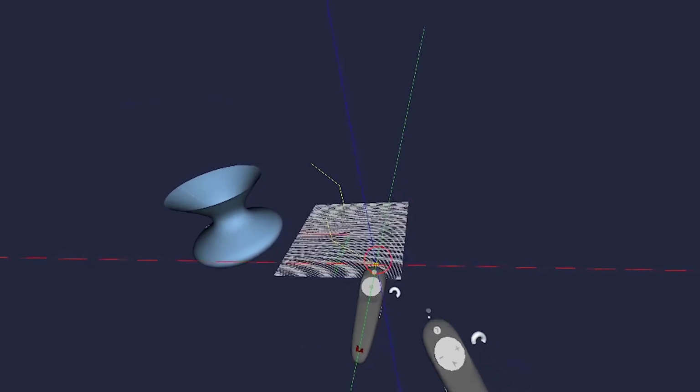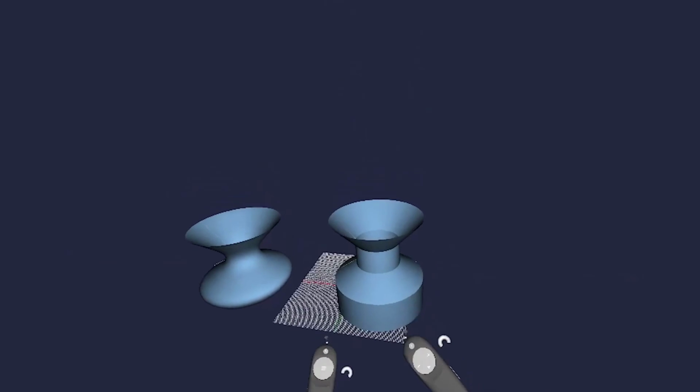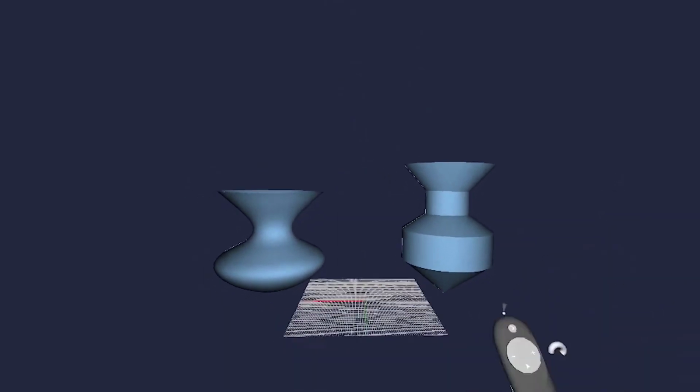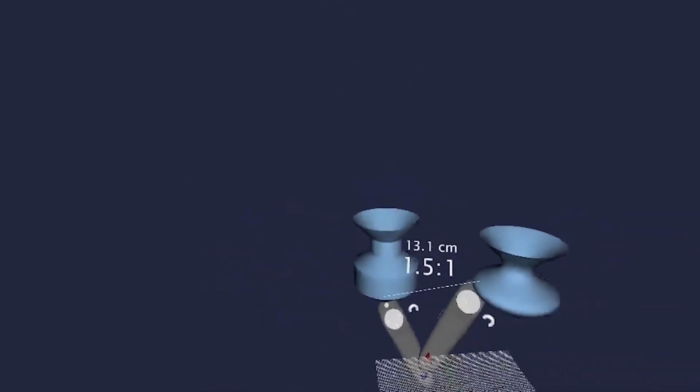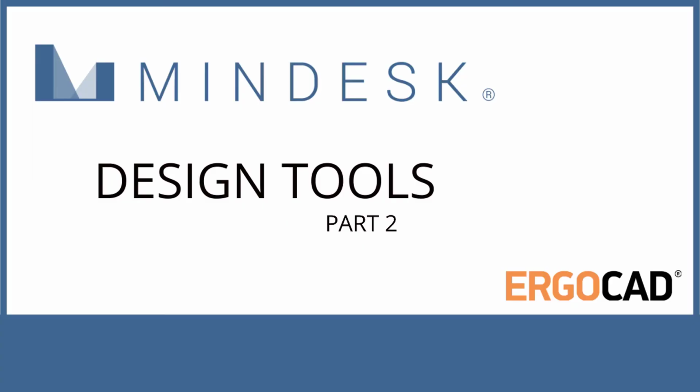Select the end point, hold it down, and revolve with your other hand until you see a 360-degree surface. Orbit around the model so you get a chance to see all sides of what you just modeled. And that's it.